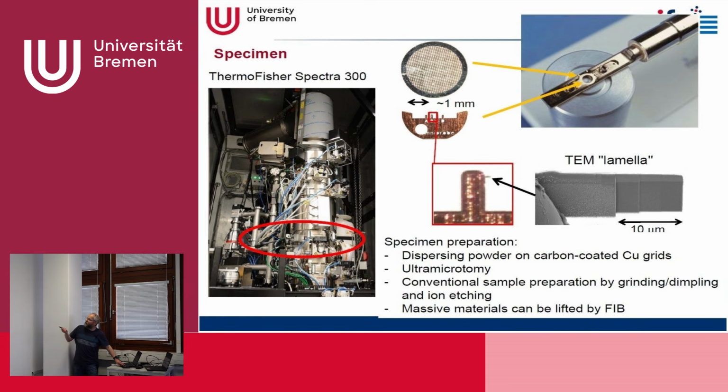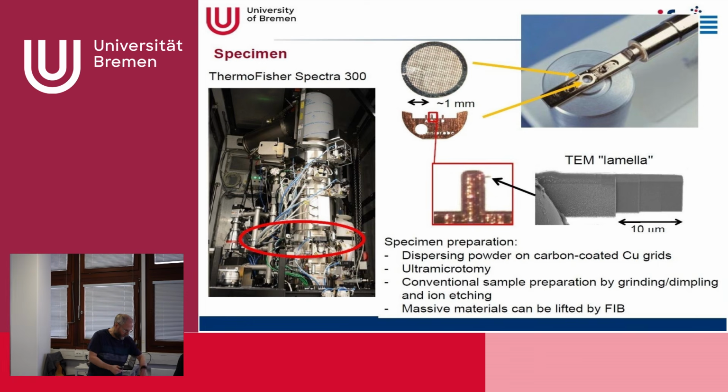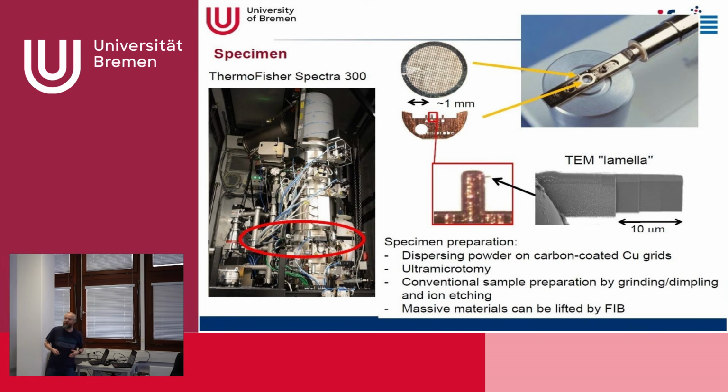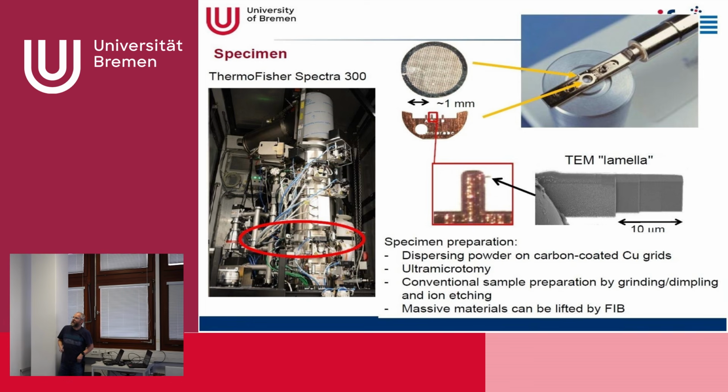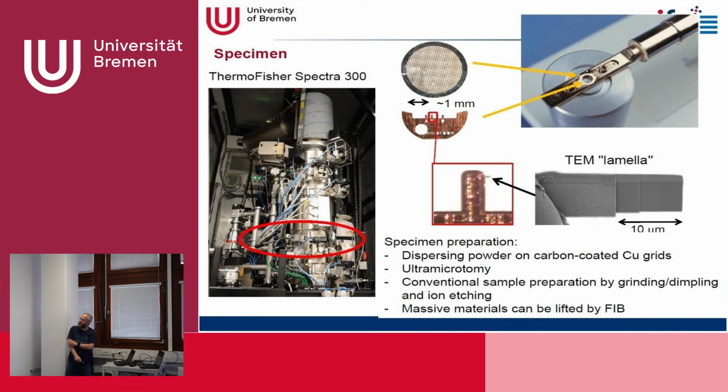Okay, so then we have already arrived at the specimen. And of course, because electrons have a strong interaction with matter, we need to do something with specimen preparation, because we cannot just enter a tool or material like this into the transmission electron microscope, because electrons will get stuck in this material. So depending on what material we have, there are different specimen preparation techniques.